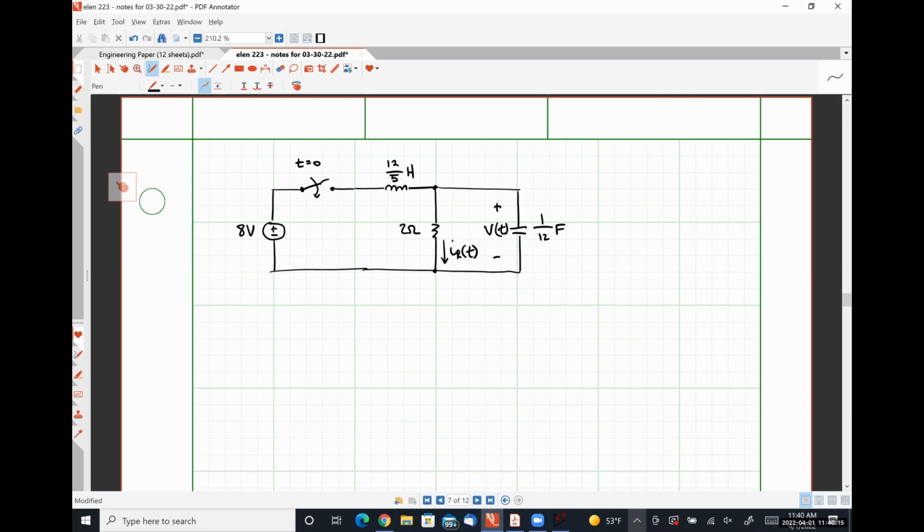So when we analyzed the last problem for the capacitor voltage, we used the capacitor voltage response equation, and then we used the derivative based relationship for the capacitor current, right? When we did our work for the inductor current, we first set up our system of equations involving the inductor current response equation itself, and then the derivative based relationship, which had to do with the inductor voltage.